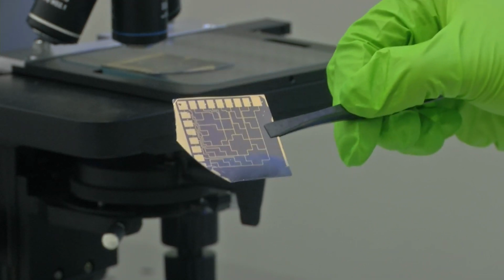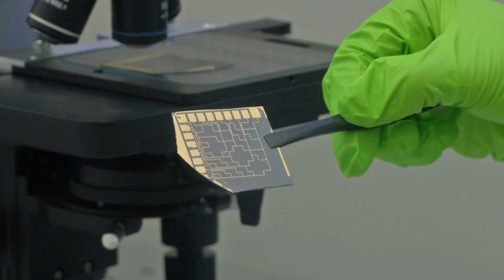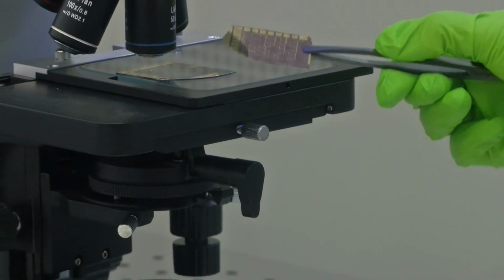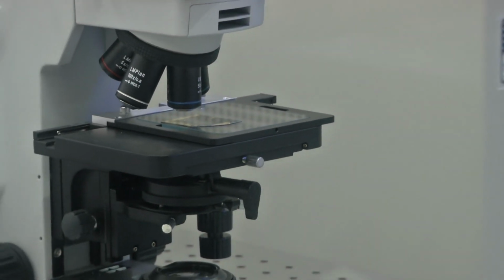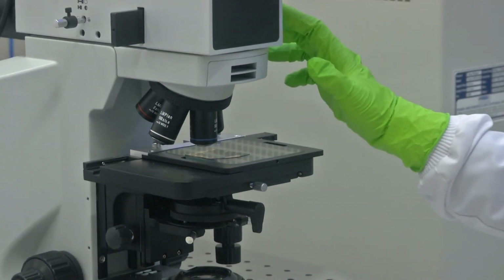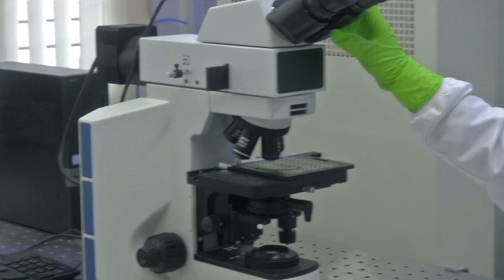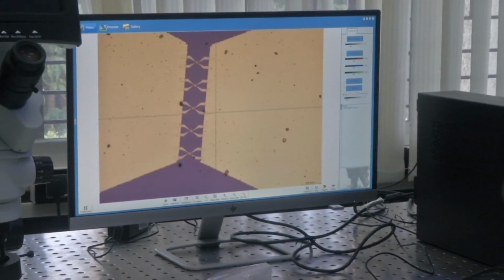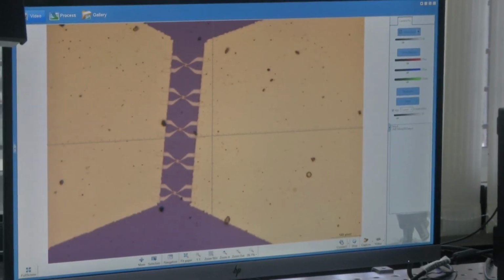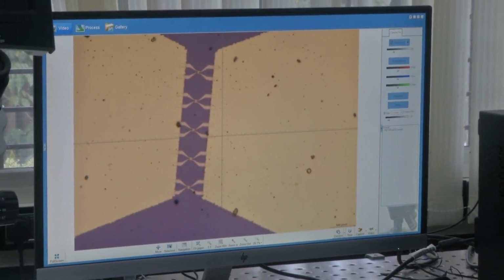Now, how do we identify the features of these electrodes which have been fabricated on this wafer? Now, let us say I put a similar one on the metallurgical microscope. I have just put the other part of this on the microscope, and then when you focus it, if you can see the one on the monitor, in between the fine lines are the electrodes, the right and the left side are the electrode pads, and then the interdigitated electrodes could be seen which is in the center, more like the canal.